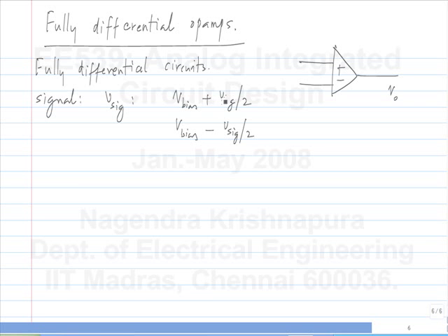Okay. What's the motivation to do this? Why would you want to have fully differential signals? Common mode? Common mode noise will be cancelled. What do you mean by that? Yeah, so one thing is, if we are going to only sense the difference between the two, then a noise that is common to both the wires will get cancelled out. Okay. So let me show this.